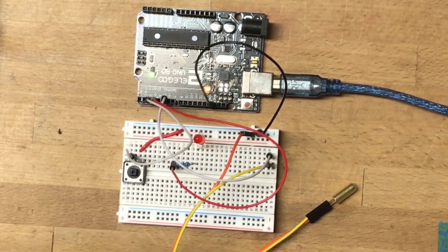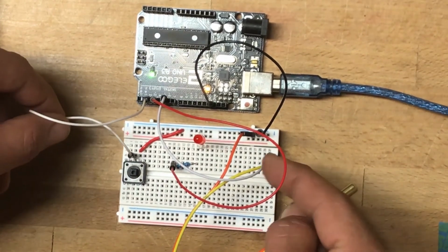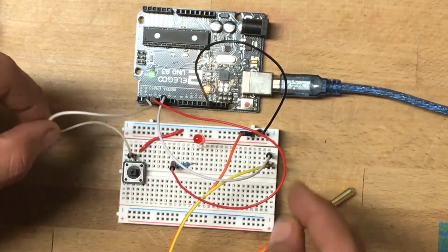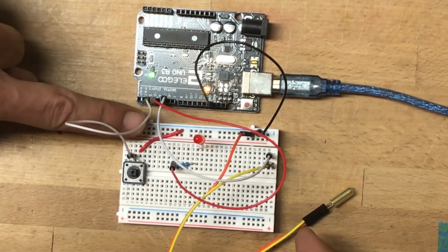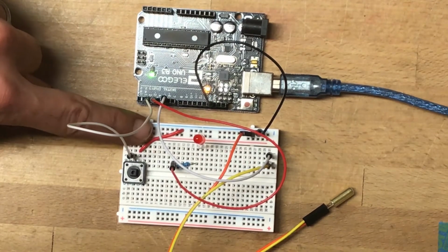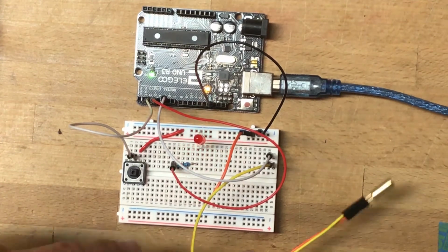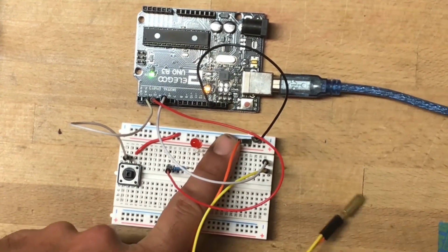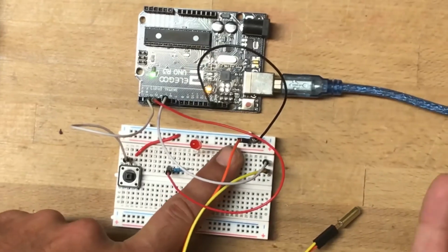And in this circuit in particular, both switches have one lead that's connected back to the board, these white wires. The other end of the switch is going back to ground. For the momentary, it's through this little jumper wire. For the tilt switch, the other lead is going back to ground on the breadboard, and then one black wire is leading back to any ground on the Arduino.